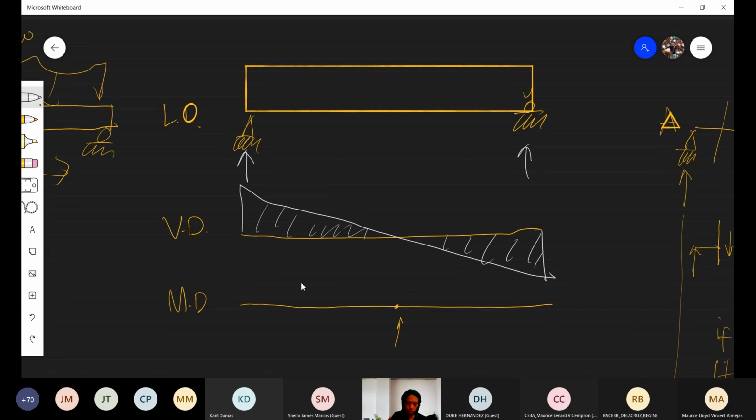When we are designing the beam due to the bending moment, we base our design on the most vulnerable section. That is usually the section where your beam will most likely fail, because it is the most vulnerable section. Your structure is as strong as its weakest link, so you have to find the weakest section to be able to design your beam properly.